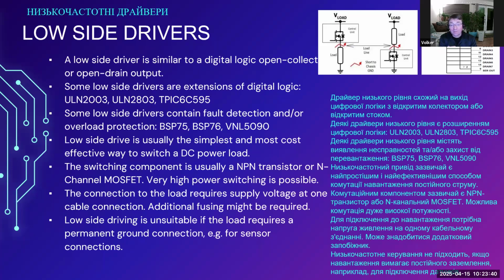In most vehicles, the chassis is ground. So if the cable gets damaged, you would create a short circuit between supply voltage and ground. So in these applications, you would have to supply an extra fuse option to make this safe.